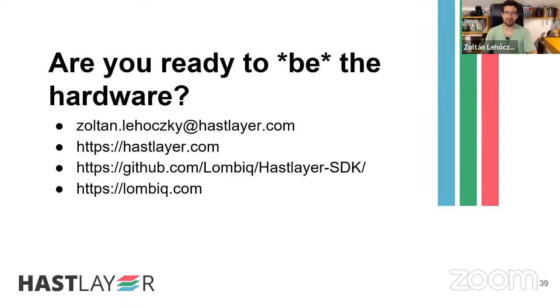Yeah, some great questions, Kelly. Let me answer that first one, because there are actually three questions, I think. So the first question is that it depends. It depends on the configuration of the FPGA itself. It's possible. What happens, just to give you a little bit of an idea about how FPGAs work, is that there's an FPGA fabric, we call that, and its configuration is kind of the hardware implementation.